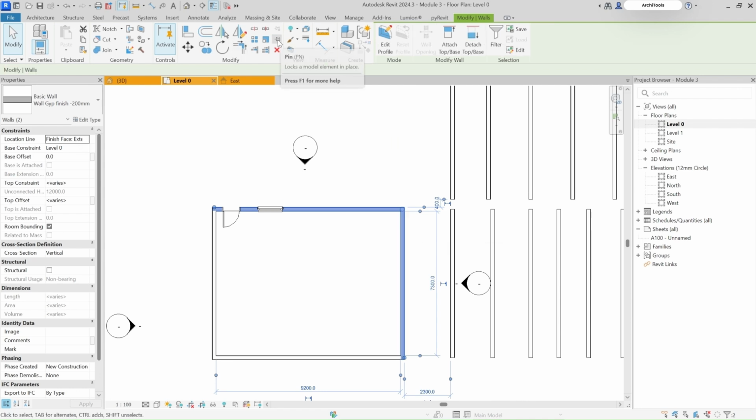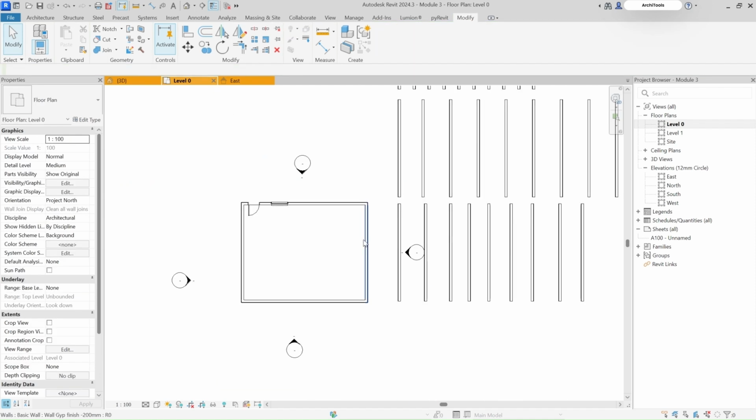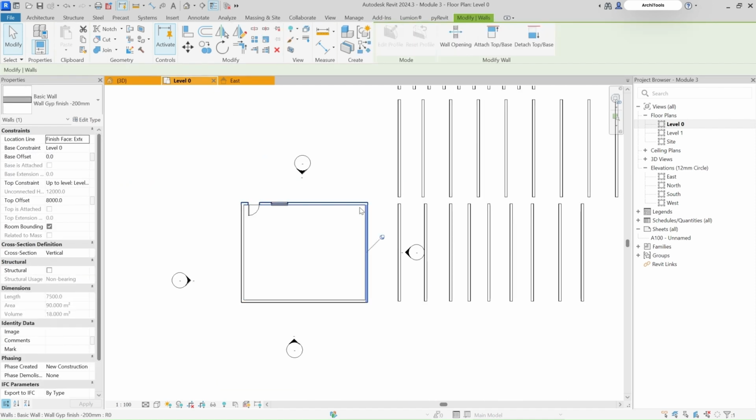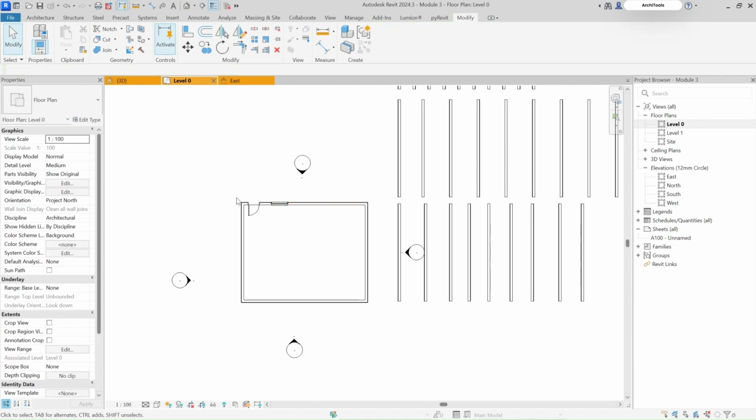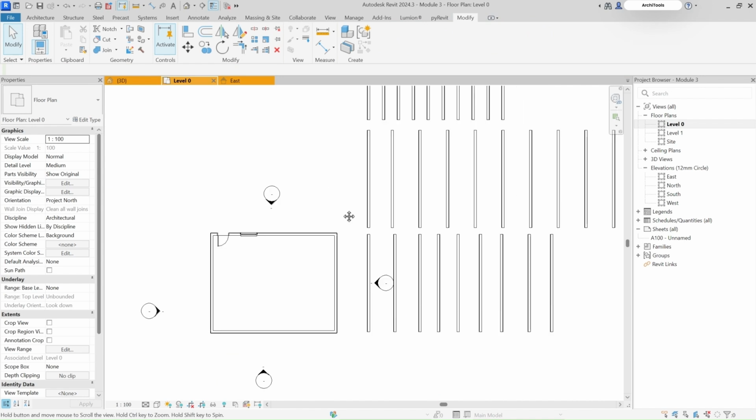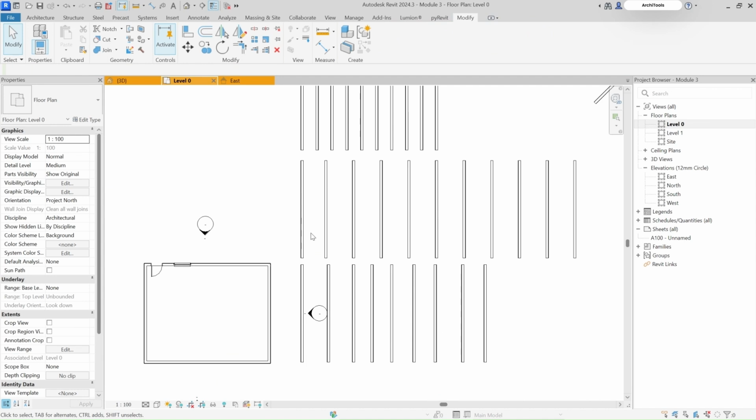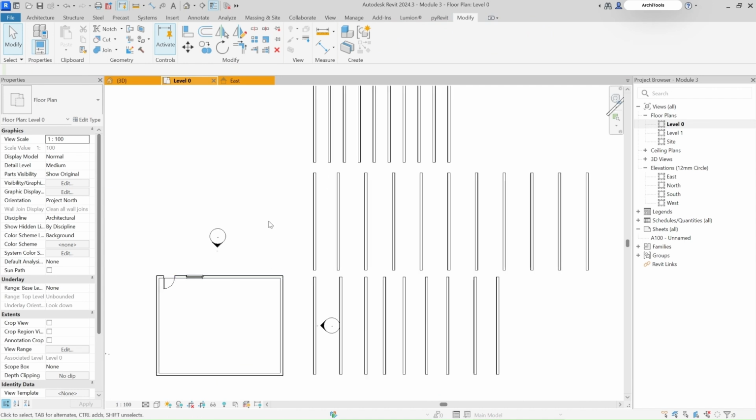So you can simply pin it from your end, and this makes sure that any other persons while working cannot, by any chance or mistake, drag it or delete it, showing a warning that the pinned objects were not deleted. So this keeps important items secure. So this is used for pinning the scope boxes and the grids, which you know are already fixed and shouldn't be moved while working. So it's a good point.